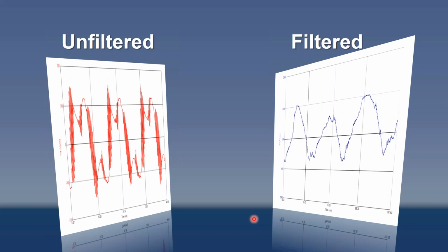So VFDs, or variable frequency drives, use high-speed switching IGBTs, or insulated gate bipolar transistors, and they create a great deal of high-frequency voltage harmonics, like we can see here. We can put a filter on it and create a relatively clean drive current, as we see in this picture.